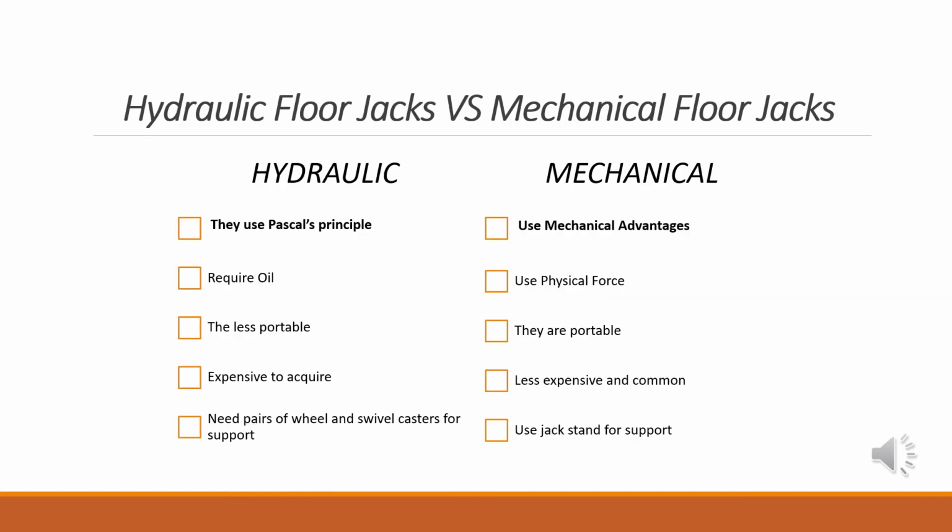This is the comparison between the hydraulic floor jack and the mechanical floor jack. The hydraulic ones use Pascal's principle and require oil. They are less portable, expensive to acquire, and need pairs of wheels and swivel casters for support. They are different from the mechanical ones, which use mechanical advantage and physical force. Those are portable, less expensive and common, and they also use jack stands for support.